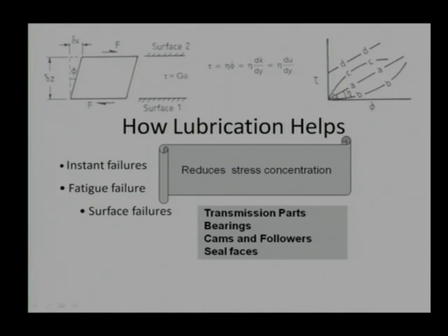are liquids which will show behavior like the CC curve, and there are a few liquids or semi-solids, for example grease. Initially they will not deform at all when shear force is applied, and once it is applied they will show Newtonian behavior. Typically this is what we call a Bingham liquid.